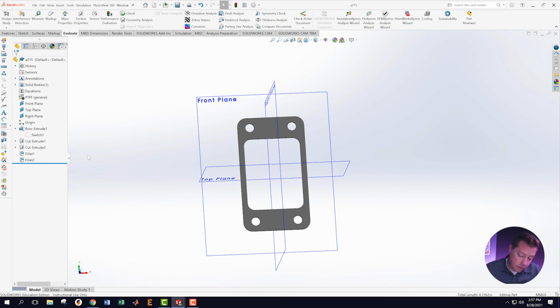Through the activities, you learned firsthand how 3D geometry is constructed from 2D shapes, such as rectangles and circles. You learned about specifying shape, specifying size, and specifying location or placement in space. You began learning about geometric relations and how to add and delete them. You learned about 3 simple 3D CAD operations: extrude, cut, and fillet. You learned how to evaluate the parts you created by doing a simple mass properties evaluation. And you learned about the importance of creating fully defined sketches and how to make them. So that's actually quite an accomplishment for about an hour's worth of work.